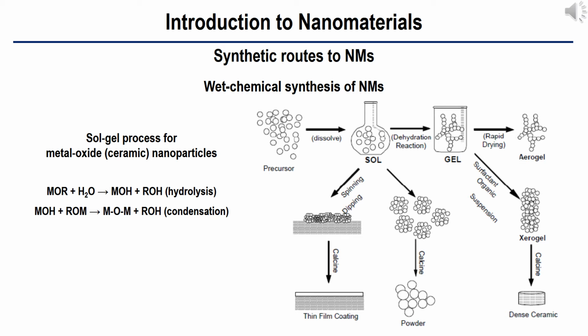Ostwald ripening, which is also referred to as coarsening, and phase transformations may occur. The aging process of gels can exceed 7 days and is critical to the prevention of cracks in gels that have been cast. 4. Drying of the gel, when water and other volatile liquids are removed from the gel network.